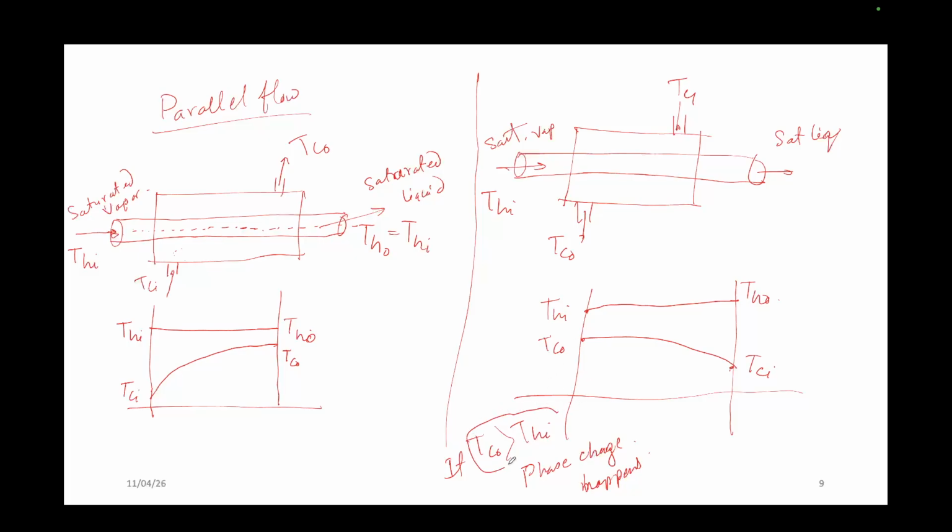It indicates a phase change happens. Where is this phase change happening? It is happening in the shell side. So that's why this graph can move this way. But if it happens in such a way, then you will see that the temperature profile initially remains constant, and after that all of a sudden it decreases. Have you got this?